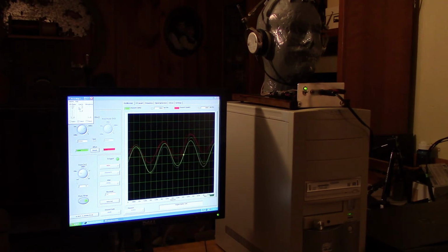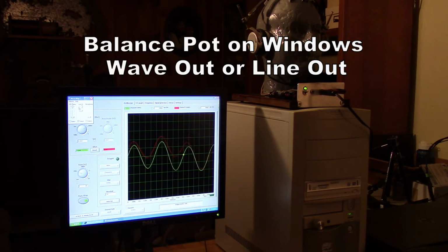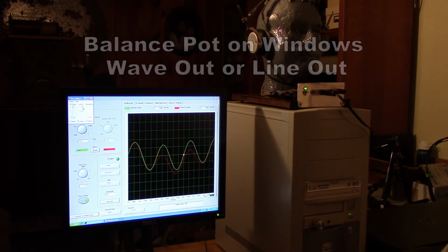So some of this is acoustic and some of it is low frequency rumble that's coming through from the computer sound card. Okay, I'm still not satisfied about that low frequency that's riding on there, but you can easily see now that I've flipped the phase on that one earphone that the two drivers are now in phase. So even with a not so perfect test system, we're at least being able to put the two drivers in phase. Also, you can see I've adjusted the line input balance here so that the two are more equal, so I could study them a little more.